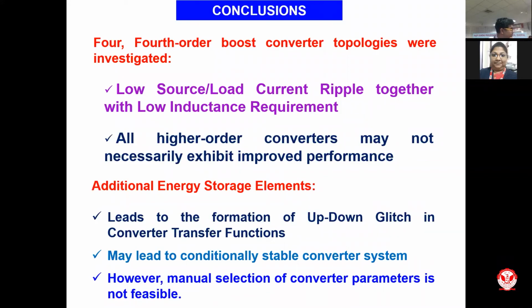So the topologies can become complicated, but you need to always take into account what the trade-off is in the design that you need to attain, whether your focus is on attaining the steady state requirements, or you also have some restrictions on the dynamic performance as well. Then you need to have a trade-off in the number of energy storage elements.